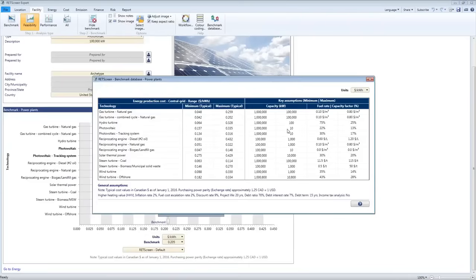If we had a small PV system of 10 kilowatts with a relatively low capacity factor, say of 13%, we have enough information given the cost of these systems to calculate what the energy production cost would be for that system. So a small, expensive, relatively low efficiency system would give us the maximum energy production cost. Conversely, if we take a very large commercial system with lots of economies of scale, much lower cost per unit, and really good efficiency, we get the lower value for the energy production cost.